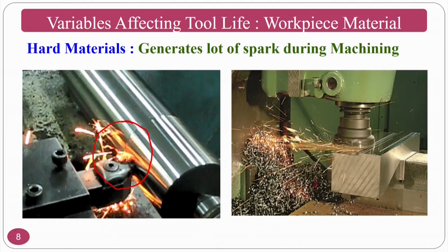At the same time, the chip is entangled in the machining region, which imparts more and more temperature onto the rake surface of the tool.